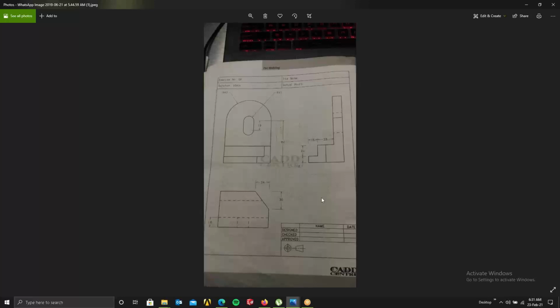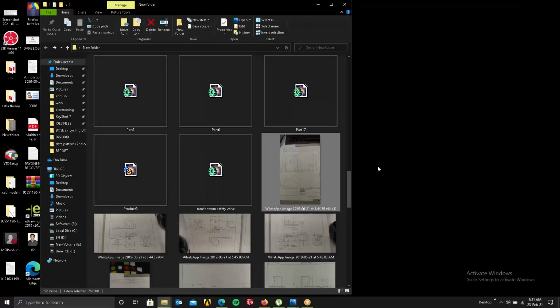Instead of that, you can take the side plane, draw this, and extrude it to a distance of how much? To a distance of 43 plus 43, 86. We can extrude it 86. Like that, you can save your time and energy, because whatever design you're doing, it should be very simple and very structured. Okay, so that's one example.